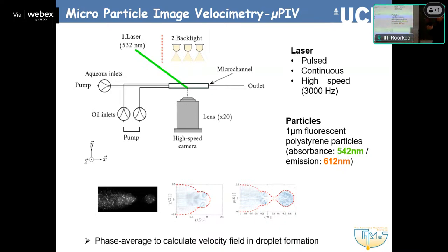The camera is not very fast, but it's called a straddling camera and can have two frames close together, and then the next one comes further down, after a long time. The laser is synchronized and controlled so that it gives one pulse in one frame and the other pulse in the other. If you had the two pulses in the same frame, you would not be able to see the difference. So it's important to have them in different frames.